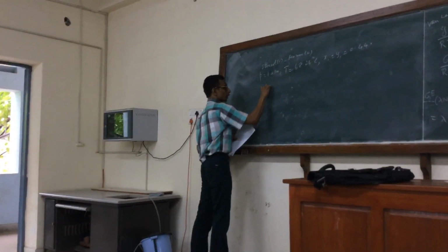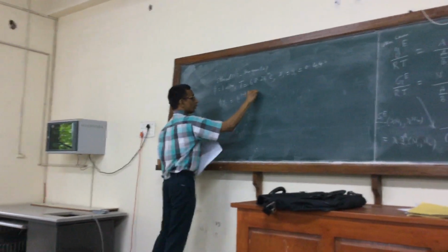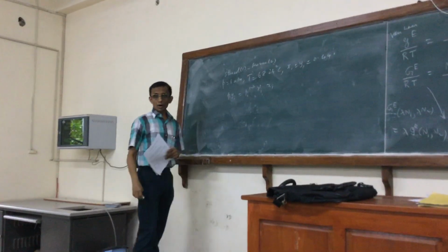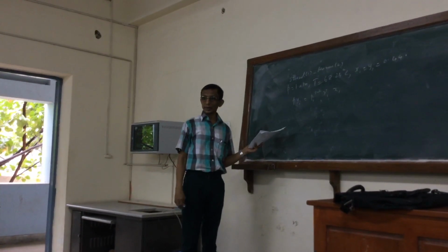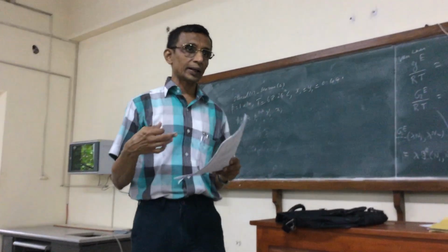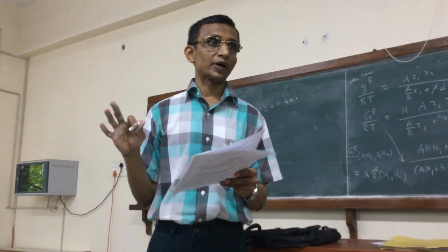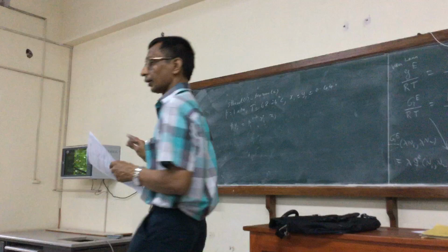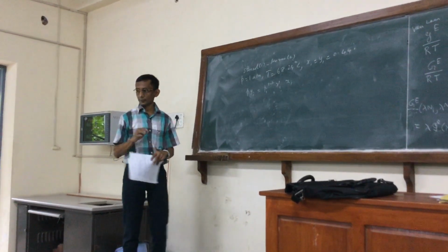I'm now going to assume that modified Raoult's law is valid. So I'm continuing to treat the vapor as ideal. Obviously, if we treat the vapor as a non-ideal gas mixture, the way you determine the gamma, the values will be different. So I'm assuming the ideal gas mixture holds for the vapor phase.